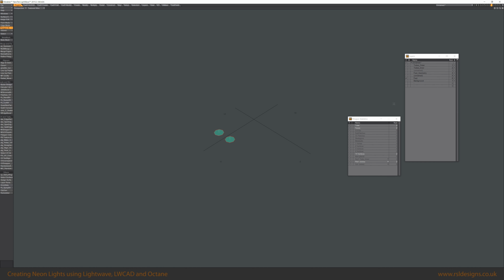So with the feet geometry layer selected in the background layer, we run place mesh and we simply use the populate function within place mesh, and all that does is it takes whatever you had in the background layer and it makes a copy onto any of the geometry that you have in the foreground layer.